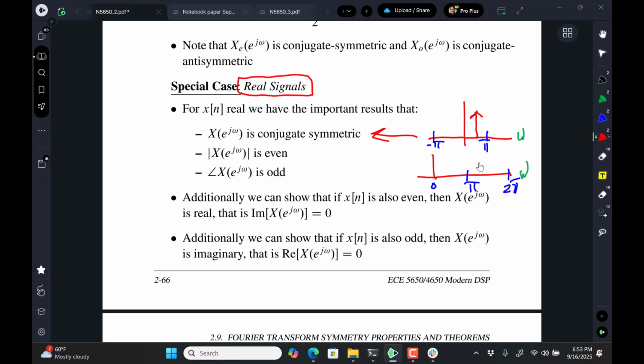So generally when we're plotting the spectra of a real signal, or plotting the frequency response of a real impulse response, what I want you to do is not waste paper, in a sense. I want you to just show this band. Just zoom in on the uniqueness of it, because it's conjugate symmetric. So the unique information is all in half the band.